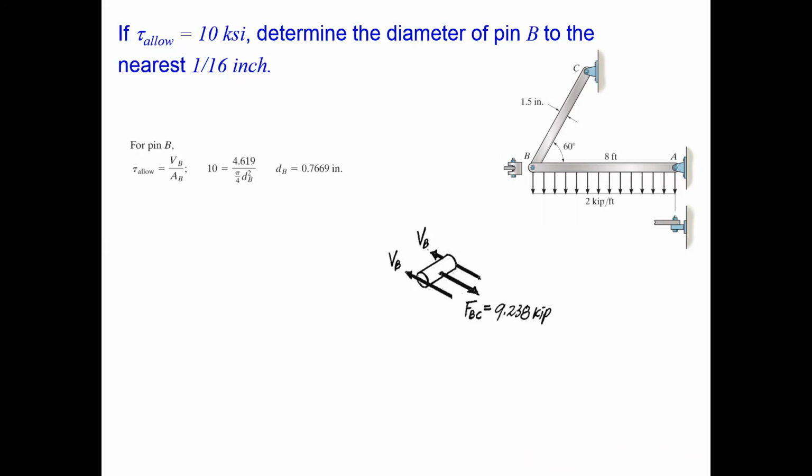All right, now we need to make sure though that the stress never goes above 10 ksi. So I want you to think a moment about what diameter you would specify, where the diameter would still have a 16 in the denominator. Okay, so if you try 12/16, you get 0.75.